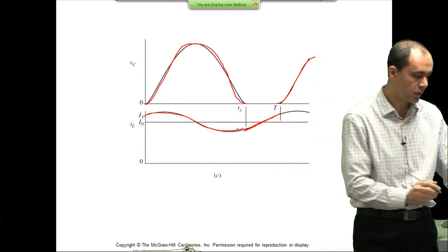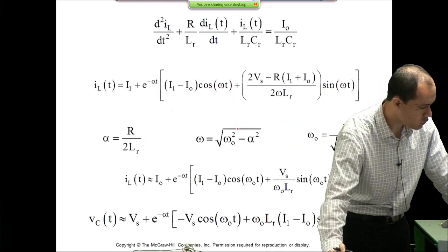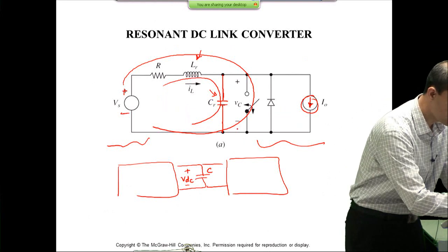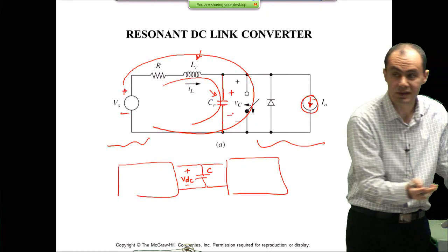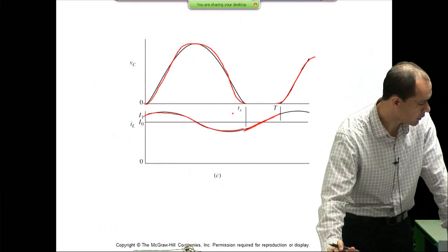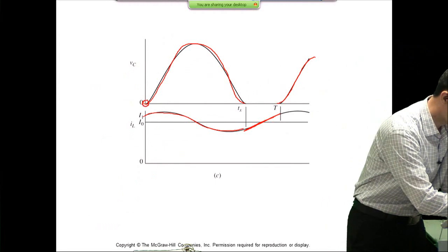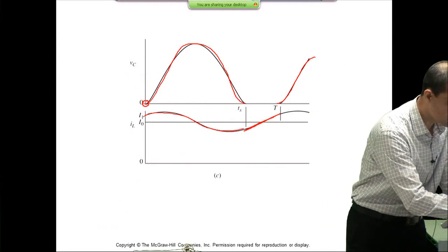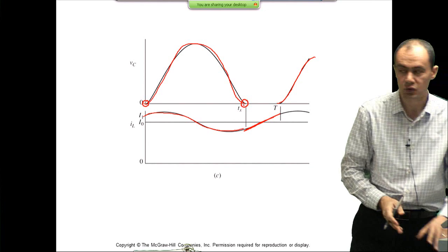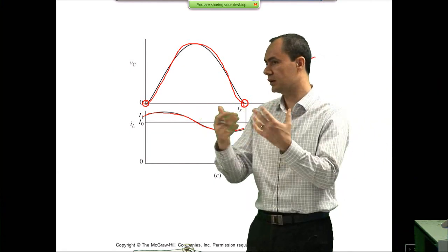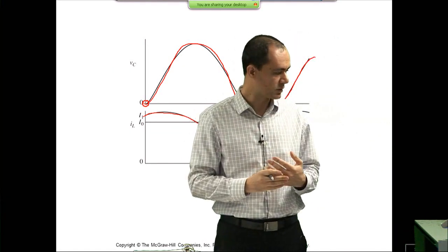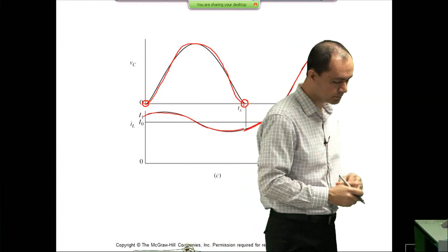So you can argue that we have the switch over here. If I focus on the voltage across the switch, which turns out to be the voltage of the cap as well, you have ZVS here at turn off of the switch, and also ZVS over here at turn on of the switch. So things are happening in terms of soft switching in a ZVS manner.